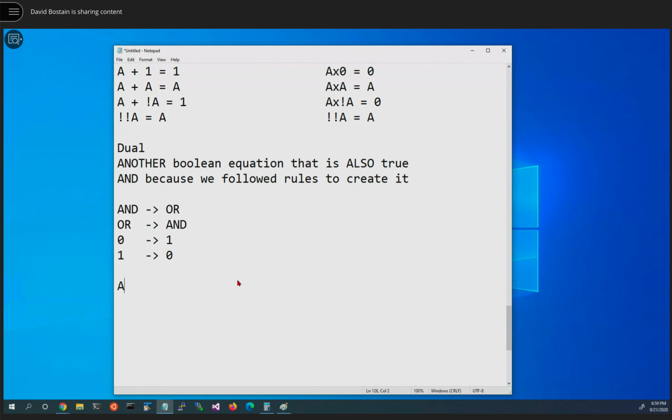If I take two things and OR them together, and then after I have ORed them together, I invert the result, that's the same thing as if I had taken both, inverted them first, and then ANDed them together. This is moving into negative logic for a second there, so if you're easily scared, hold your ears for a second.